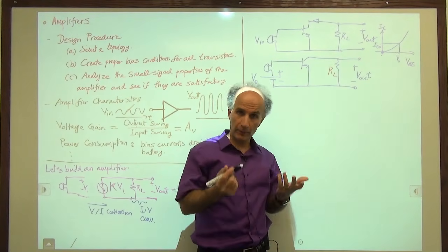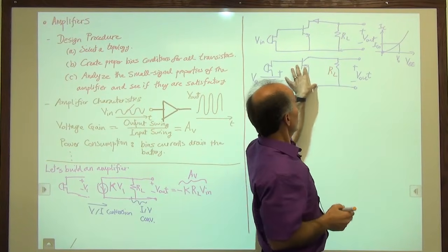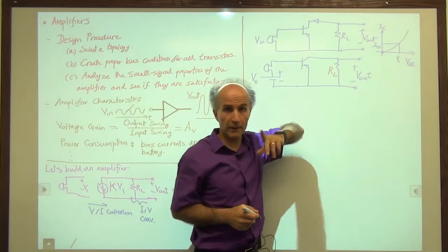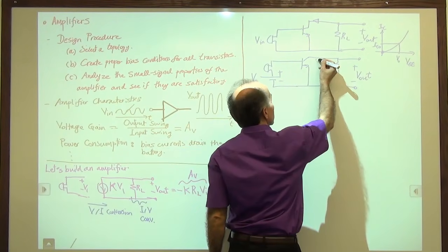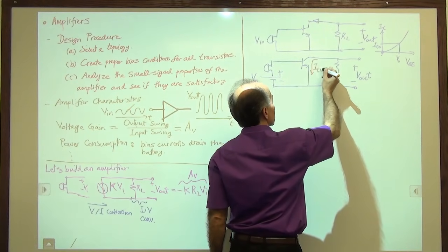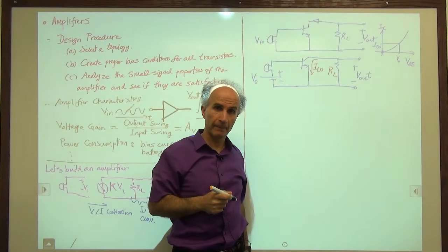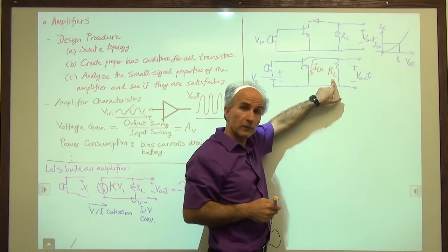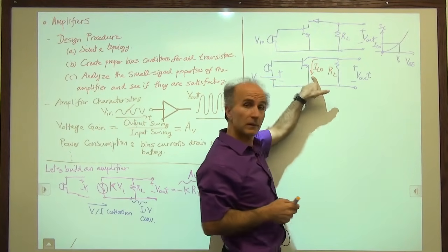All right, there's another perspective to think about that. We are thinking that in this topology, we have a certain amount of current. Bias current, let's say 1 milliamp. Okay, so 1 milliamp of current is flowing this way through the device. Where does this 1 milliamp come from? Well, it has only RL to flow through, so can it come this way through RL?